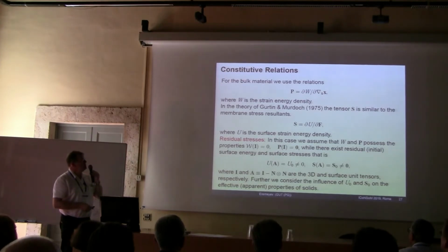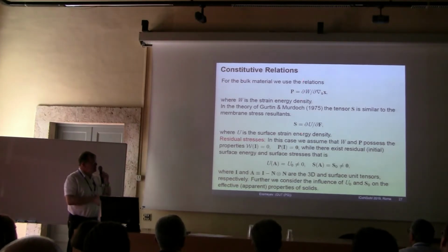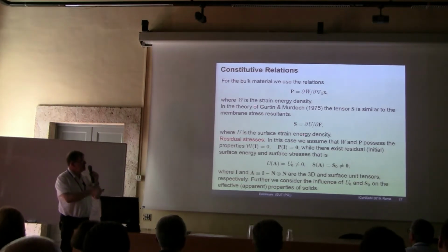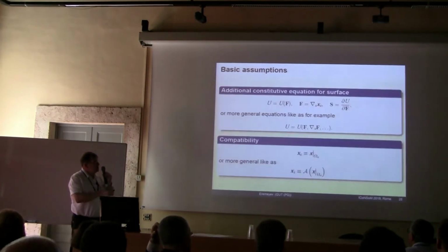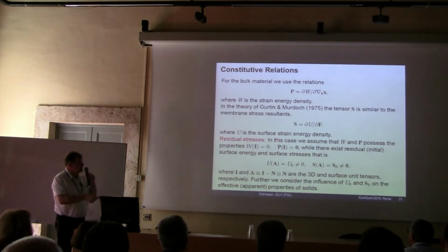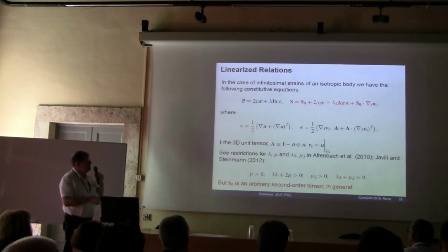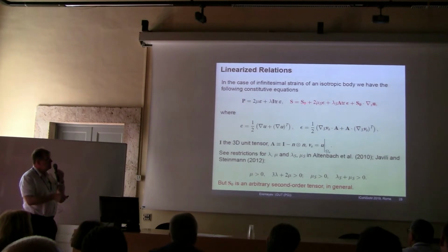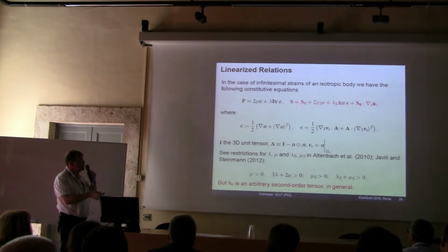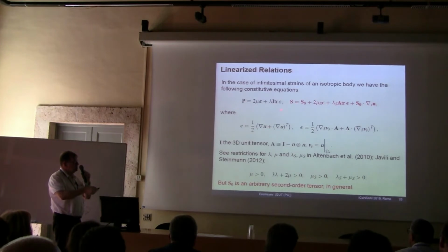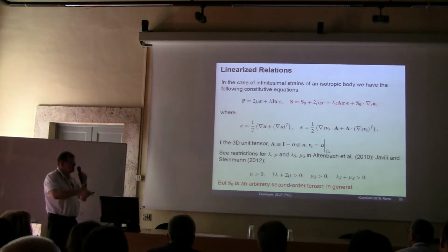Okay, coming to constitutive equations. We have nonlinear elasticity. Here we have membrane theory in the case of Gurtin-Murdoch. Because they are independent, we can simply introduce residual stresses here. And for example, if we need to solve something simple, we have Hooke's law here, and we have some linearized Gurtin-Murdoch theory where we have the initial surface stresses here, and strains here, and surface strains here, etc.